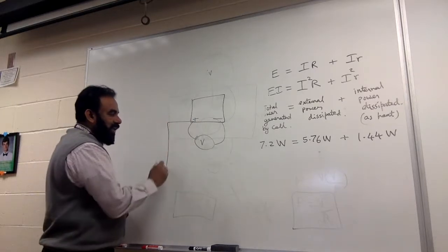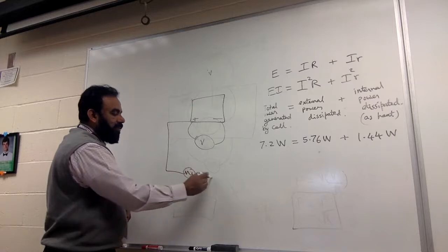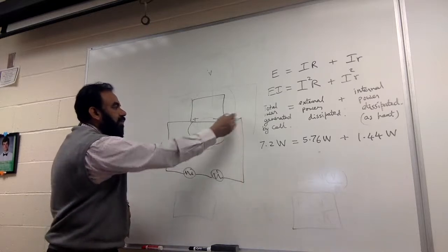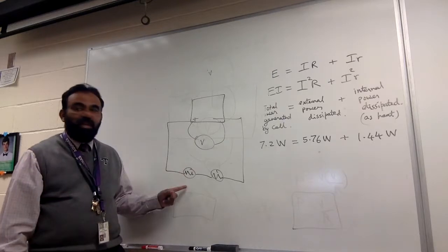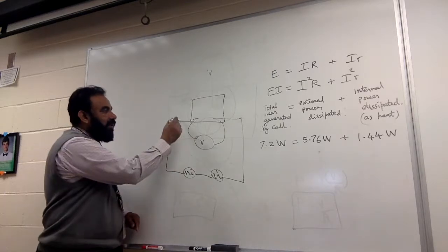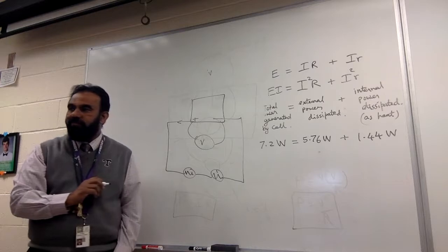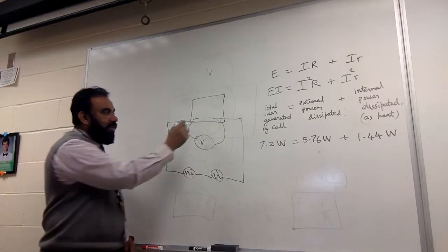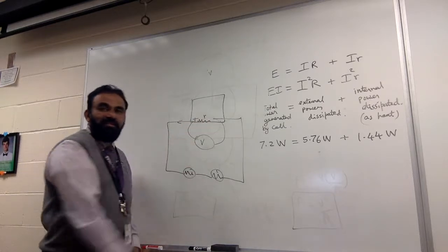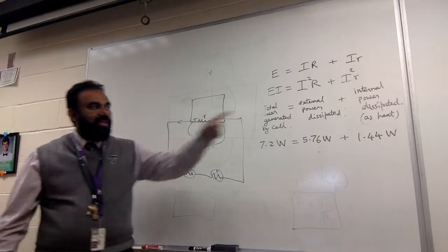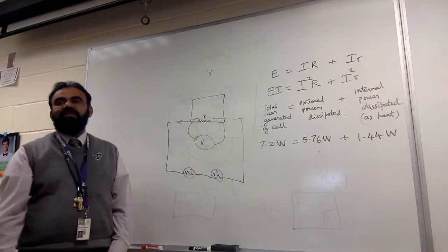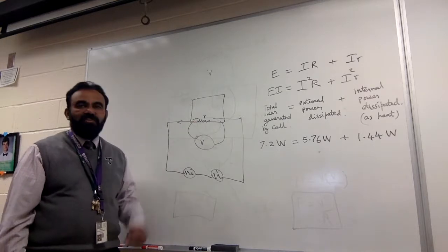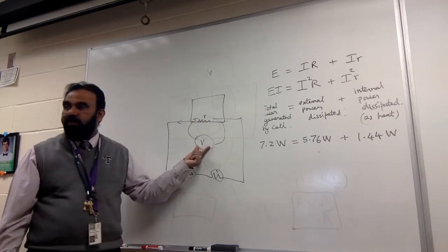But as soon as you connect some light bulbs and they are turned on, what's happening now? The light bulbs are working because current is flowing, right? And when the current is flowing, there is an internal resistance which is going to take this drop. So there is an internal drop right there. And because there's an internal drop, will this read 12 anymore?